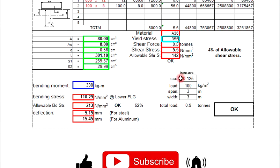If you change 235, this one will automatically change to 94, and then the allowable bending stress is 1.1 Newton per millimeter square, or 141 megapascal. So this one is the percentage from the allowable, 78% that we are using, or almost near the allowable bending stress. So you can change the size.